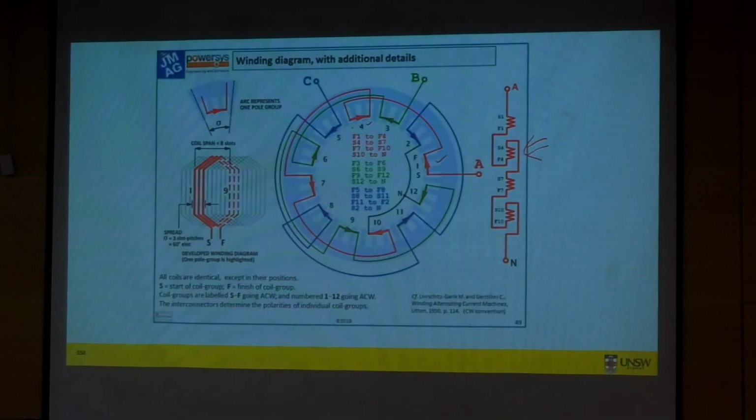If you connect the other way, then the EMF induced in coil number 4 may be subtractive. So that all the EMFs are summative, additive, you may need to connect a bit differently sometimes. It comes from some experience, but you can look at this material.